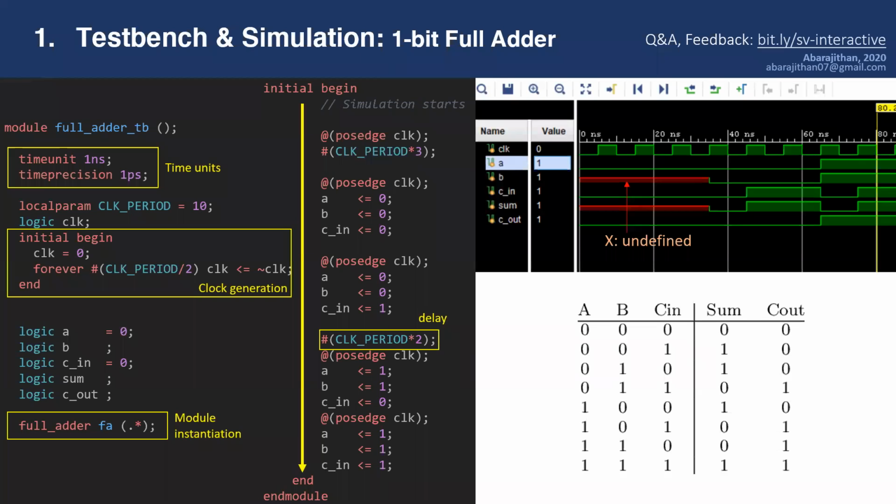If you think like that, then there will be a question: if full adder is a class, can classes have methods? Can they have functions and everything? No, they can't, because it's a circuit. You can't put a method inside a circuit. So those things don't translate. The idea is kind of similar, but don't think of it as a class and object. There are classes in SystemVerilog. SystemVerilog is an OOP language. There are classes, there are objects and everything. We will talk about it later in the next few examples. But this is not a class.